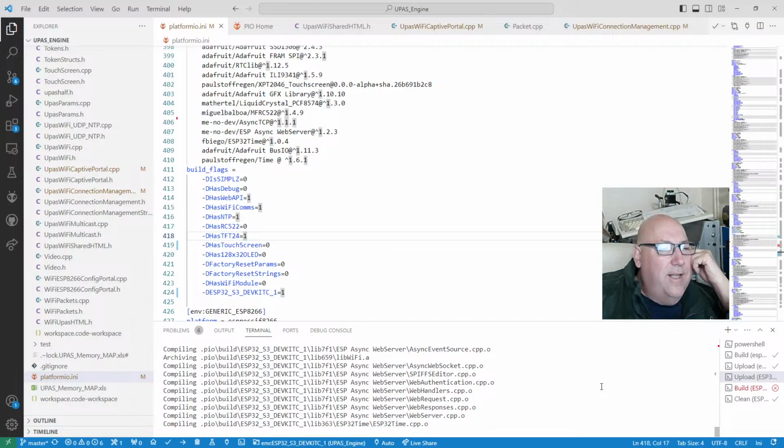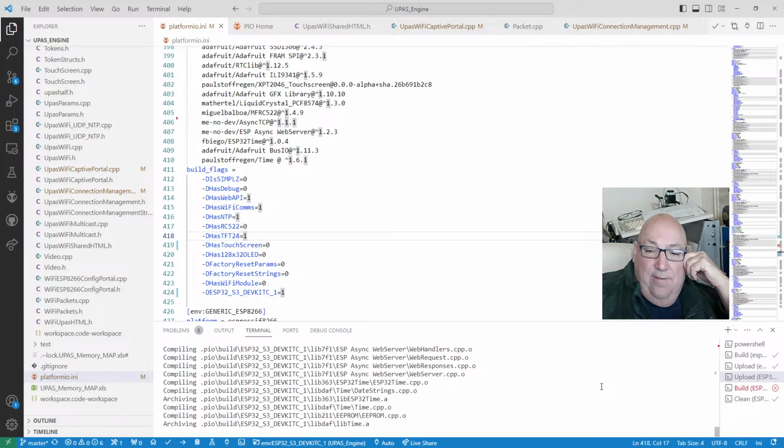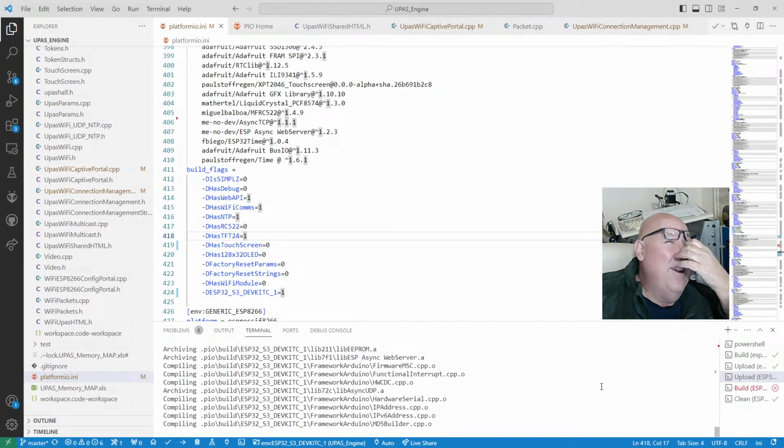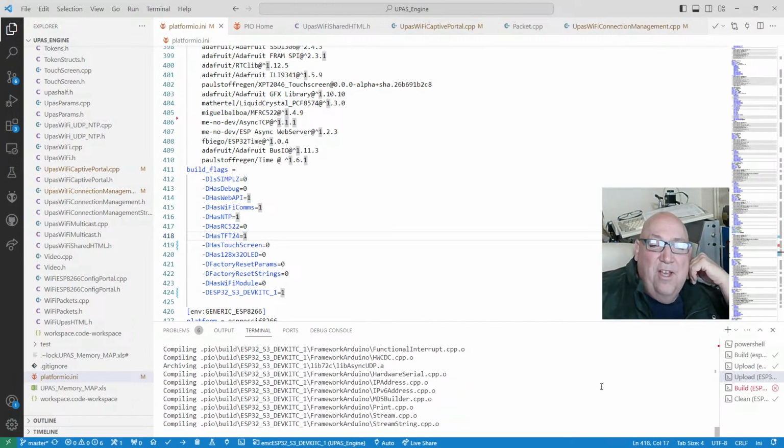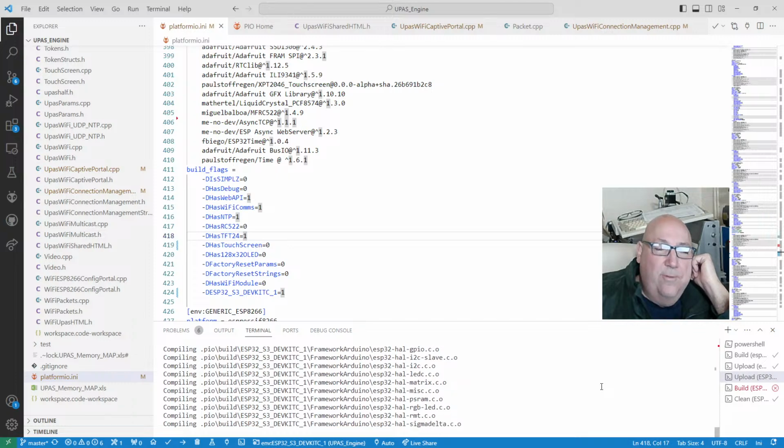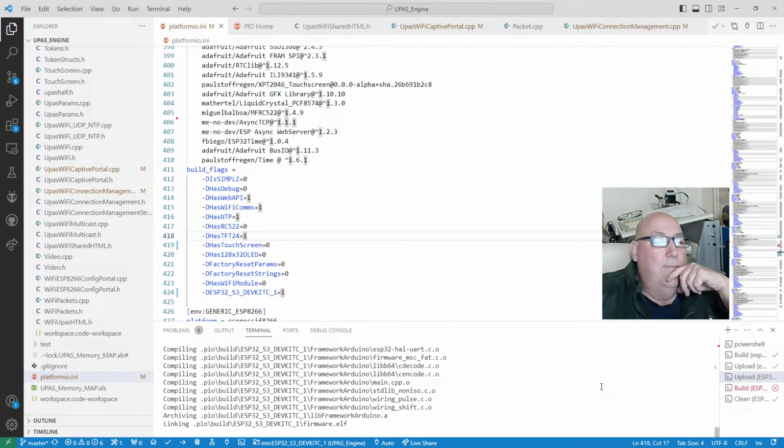So I'm doing all this just to get that. Mind you, you never know. I don't think I'm going to ever use one of them. You have to look at all the pins really to find out which pins are being used. It's a big job to work out every pin. That Node MCU, I had to go through and work out all the pins, what they did. Some of them haven't got pull-ups or pull-downs, so you have to put your own in. Some have got them, so you don't need to put your own resistor in. And to actually come up with a circuit board that you've used every last pin.